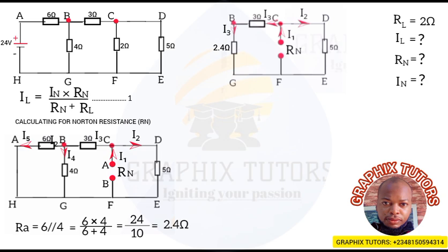Because it's I3, the same current that is flowing through these two resistors, you see both of them are in series. So you represent them by saying R B is equal to what? 2.4 plus 3, and that will give us 5.4 ohms. So I'm going to now make this only one single resistor, my 5.4 ohm. Remember, I have made the 3 ohm and the 2.4 ohm become one because they're in series. I added them together. So this is my R B. Now we have a champion. R B is my champion, which is the 5.4 ohms.